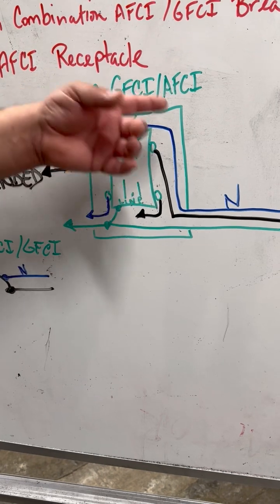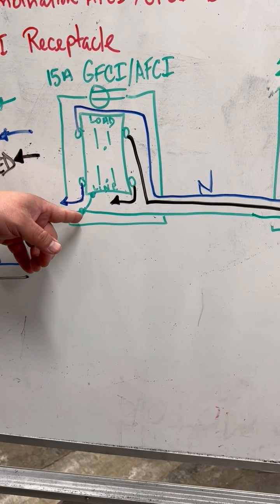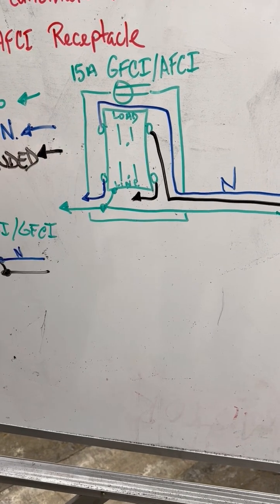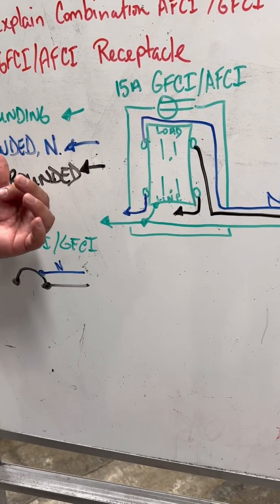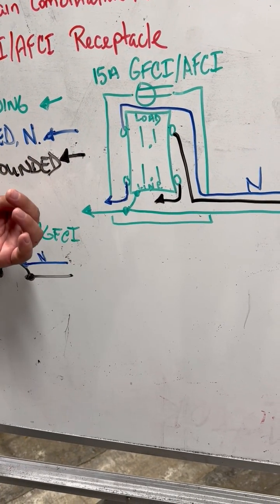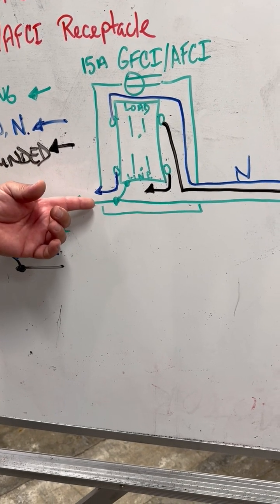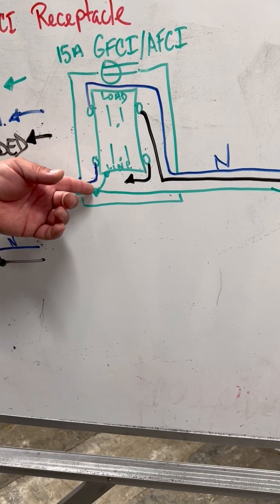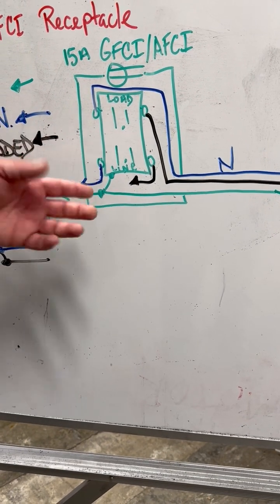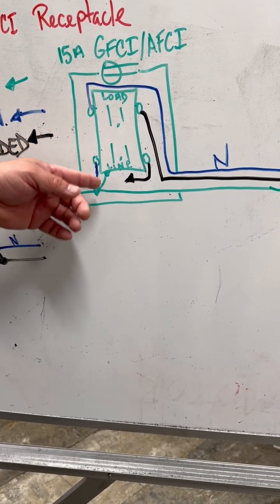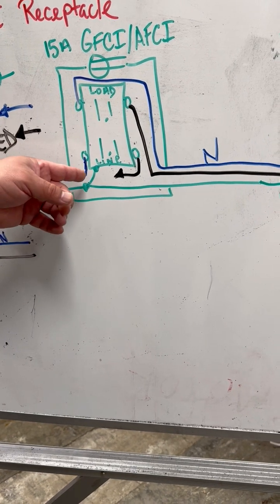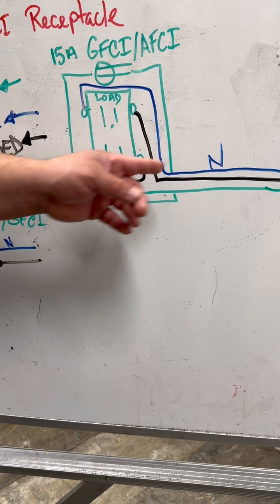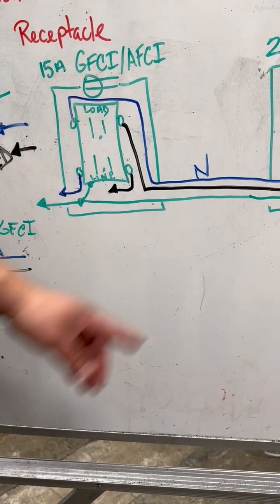I have a box here outlining. I have my raised grounding nipple at the bottom corner. Why? Because I know that my incoming conductors are coming from this direction. So when it comes in, the first thing I have them do is tie down that bare copper, lock it in, use a green wire nut, terminate on the device, and then continue on with that connection to that originating grounding conductor and continuing on to the last device where here it's terminated.